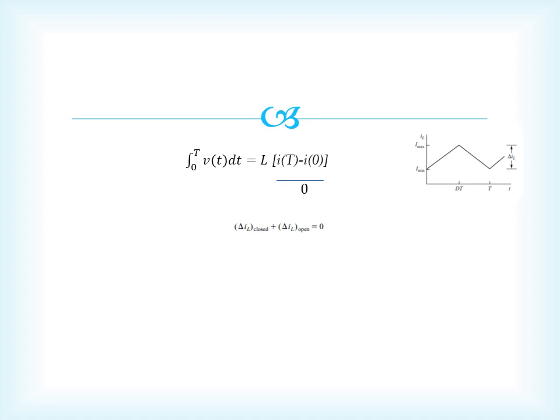It is simple as that. In the analysis which I have presented in the videos, I have used this concept. For the steady state, the net change in inductor current during the time for which it is connected across the supply voltage and time during which it is not connected across the supply voltage will be 0. So this expression has been used to analyze a circuit. This is what the steady state means in case of inductor.